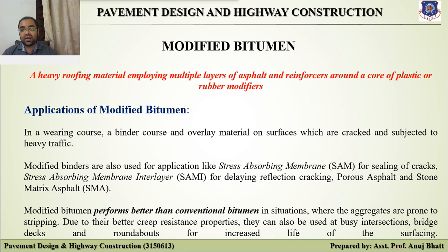Modified binders are also used for applications like stress absorbing membranes for sealing of cracks, stress absorbing membrane interlayers for delaying reflection cracking, and porous asphalt and stone matrix asphalt.